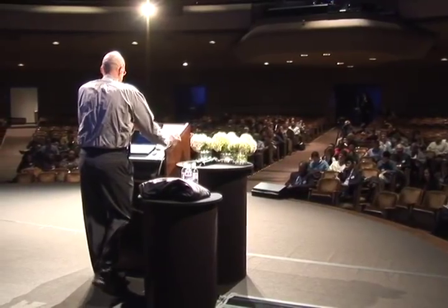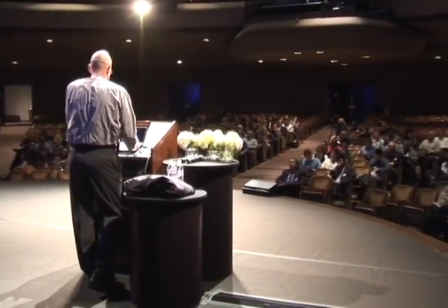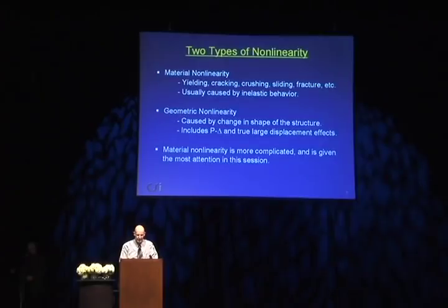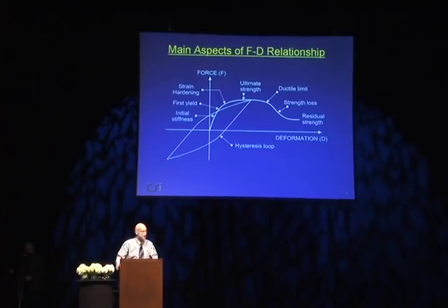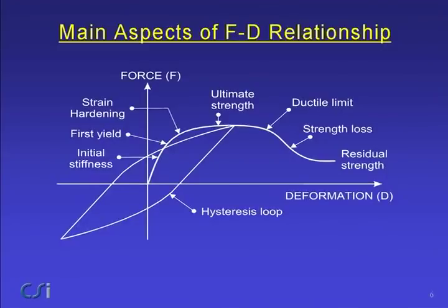You almost never, and probably never, need to do large displacements analysis, and if you do, you're simply wasting computer time. The material nonlinearity is the more complicated of the two, and that's which I'll give most attention to in this session.